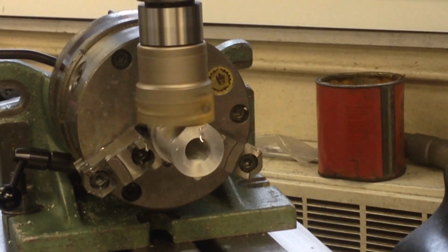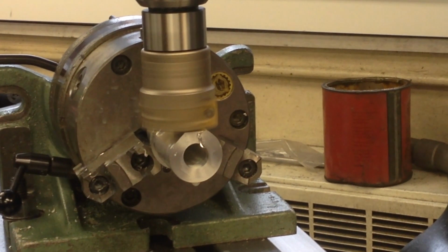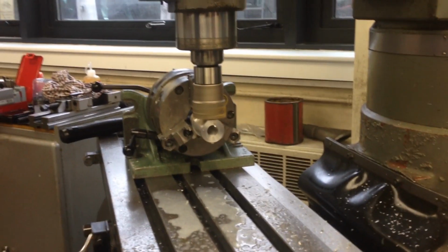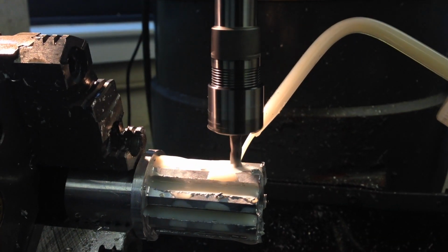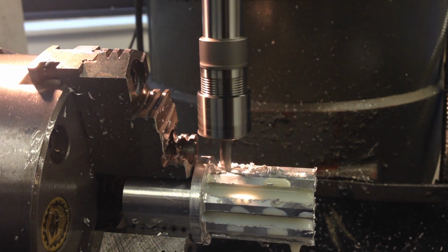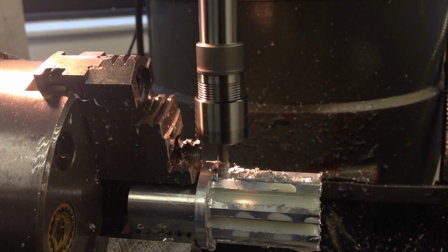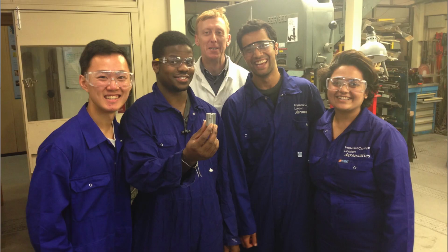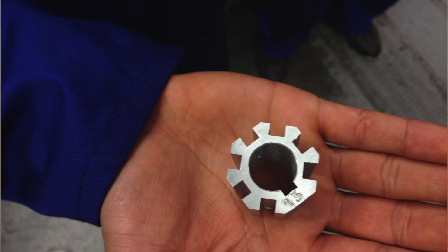On the milling machine, we turned our cylindrical block into the octagonal hub that we designed. We did this by using the cutting tool to cut a plane, rotate the vise 45 degrees, cut another plane, and so on until we had the 8 faces. Next was to use a slot drill to create the slots in the same fashion that we did the planes. After that, the last process on the milling machine was to just use a drill to make the hole for the grub screw. The last process we used was going to the broaching machine to make the keyway by removing material using a hydraulic pump.